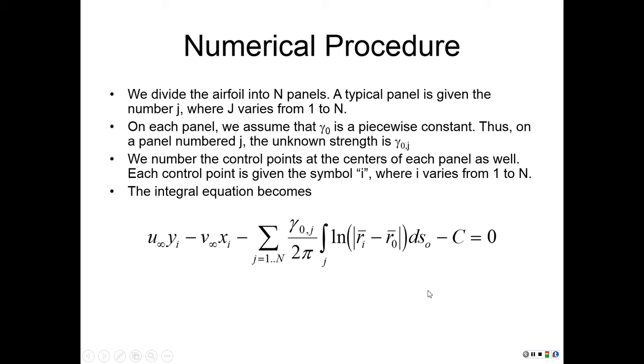It may sound confusing. So aerofoil is made of J panels. Their centers are at xj, yj. So you compute all the induced velocity due to all such J panels from 1 to n at this fixed point I, at the center of a panel called I. So this is the stream function that must equal constant. Now if you notice, this is purely a geometric function.